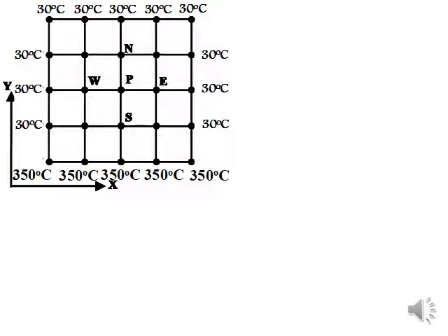But you can start with the values in the memory, like 30, to watch what will happen for the water when it comes into contact with the hotter surface. So again, whenever we don't know a boundary temperature, we can rely on the background temperature until this is updated by realistic calculation, so that 30 is the boundary temperature on the eastern and western side.